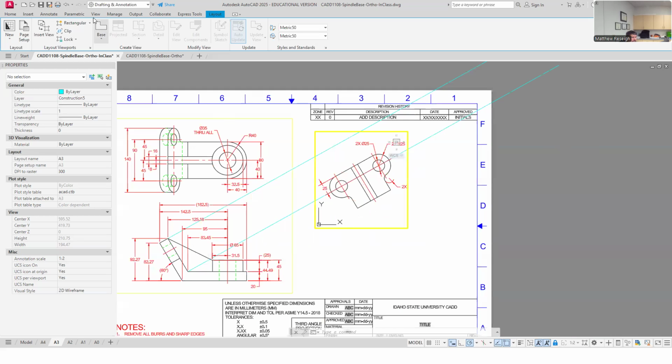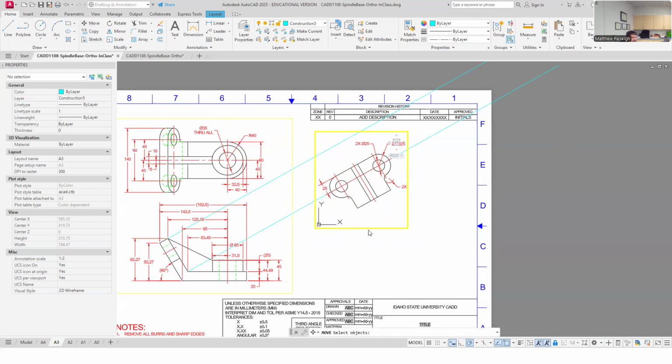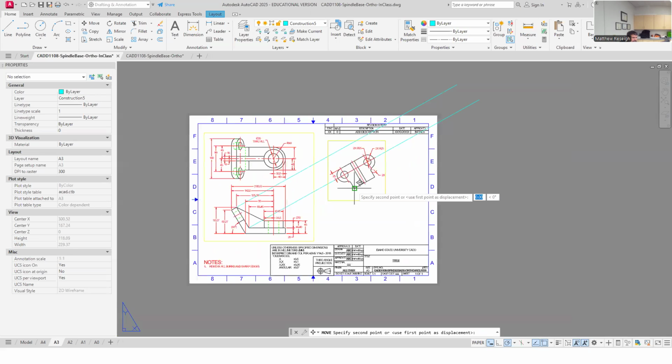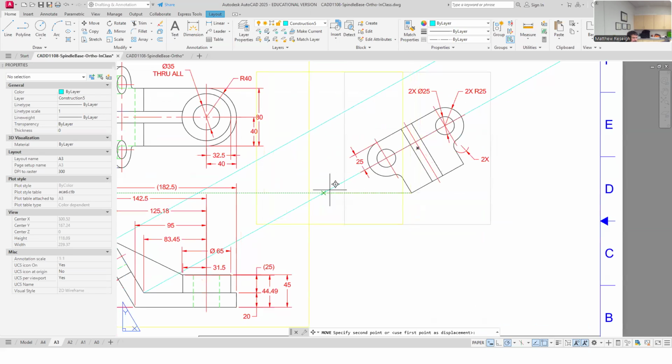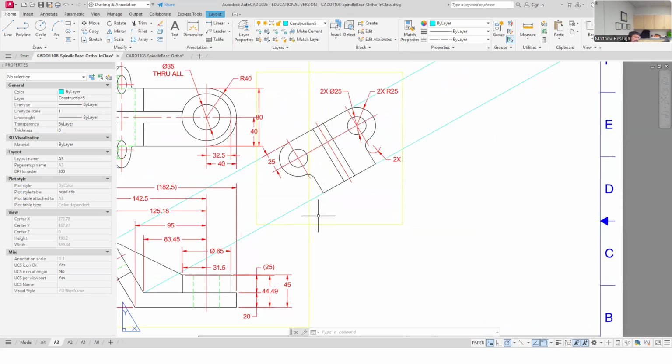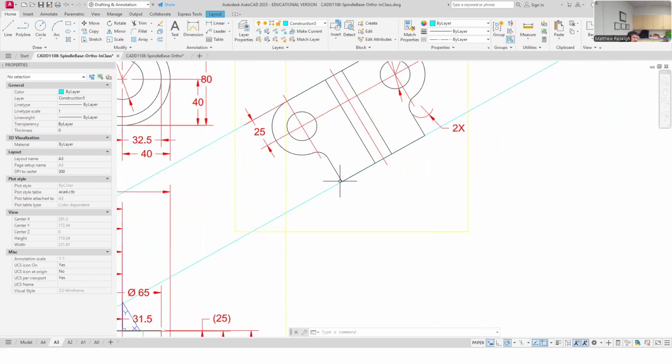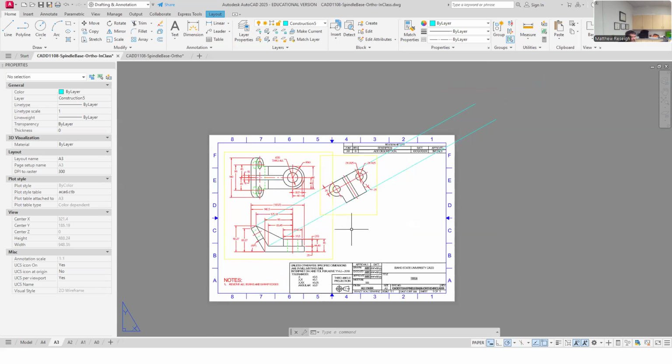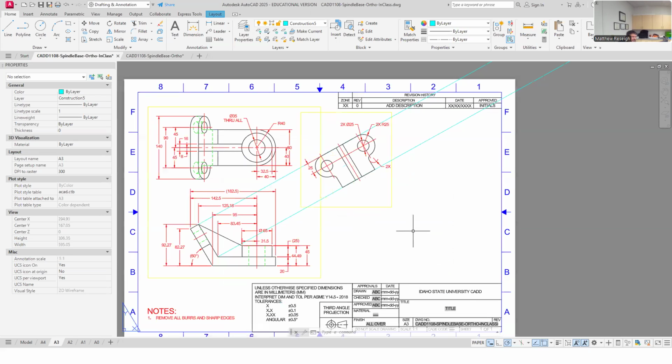And then I've got to move it into orthographic alignment. So I've got to move that viewport. Move. Viewport. First, I've got to get out of the viewport. Escape. Click, double click, triple click. This thing, I'm going to move it by this thing that's definitely going to be part of the orthographic alignment. Maybe here at first. It's a little too close, so just move it again. I move it by the whole viewport, but with this little grip maybe. Slide it along that axis a little further away. Something like that. Yeah, then I'm clearing that. So that's just a quick way to snap that thing in.